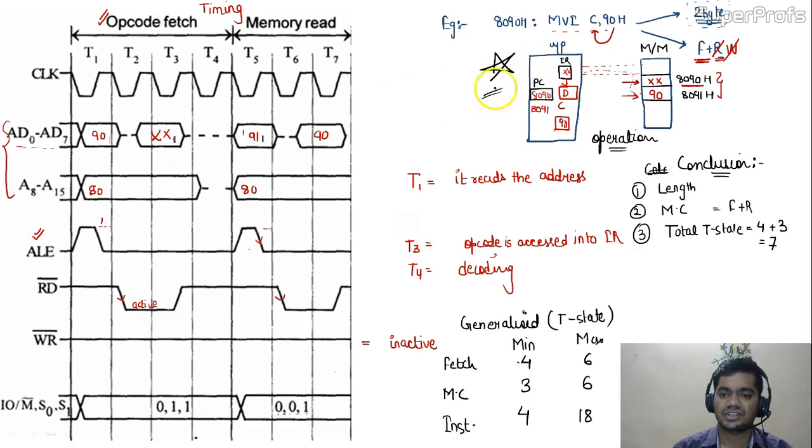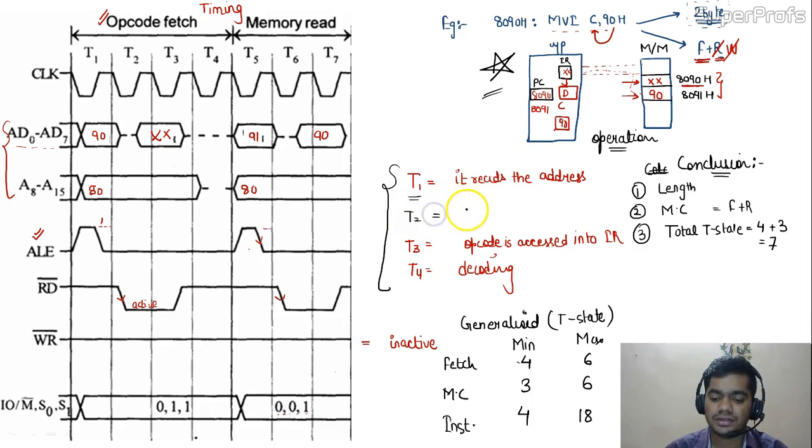So this was the instruction operation timing diagram, as well as some of the important points regarding the T states. Sometimes the question is directly based on these T states. It may be asked in T state 1 what the working is. You can write for T2 also. In T2, ALE becomes 0 and AD0 to AD7 works as a data bus. And you can see that in T2 state only the read signal is available. So these are quite peculiar, important points regarding the T2 state.